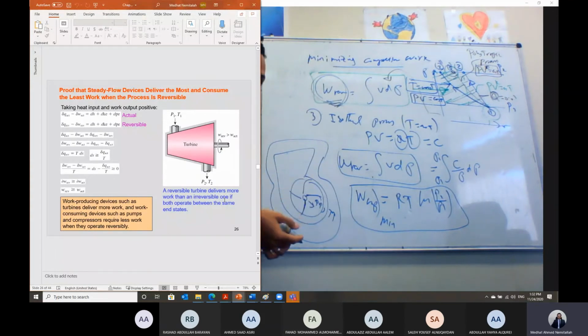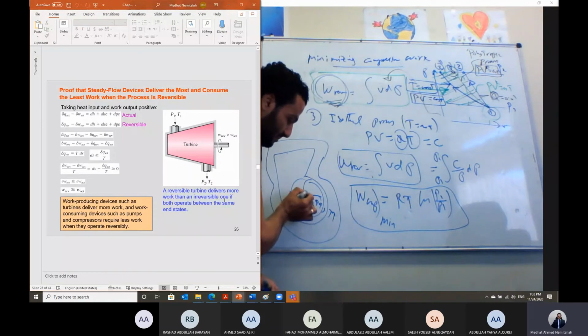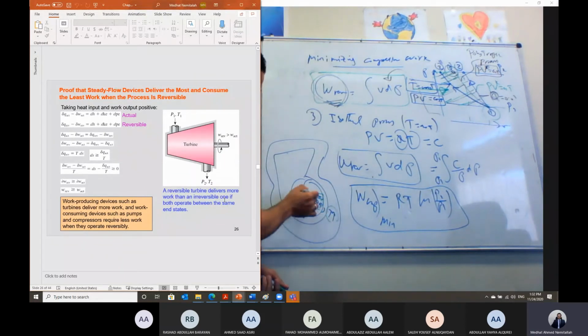It will reduce the final temperature a little bit, but I would have to apply a cooling system around each blade. But is it possible to have a cooling system around each blade, which is rotating with very high RPM? This shaft is rotating at 3000 RPM or something. Can we do that? No, it's too hard.